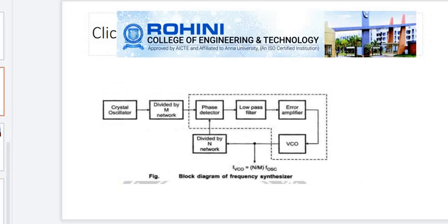The divide by N counter is realized with a programmable divider, and therefore it is possible to achieve a multiple of the reference frequency. By using harmonic locking, frequency synthesizing can also be obtained. The locking is achieved with the harmonic of the reference signal. So the voltage controlled oscillator frequency is set to a multiple of the input reference frequency. This is the drawback of this frequency synthesizer: in this method the lock range reduces when successively higher and weaker harmonics are used for locking.